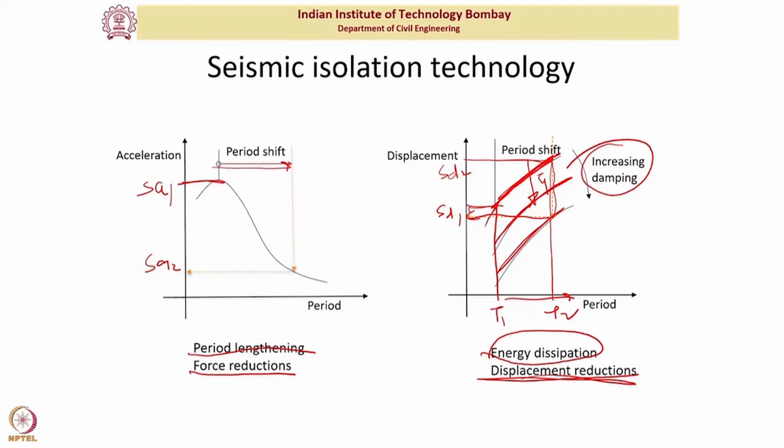So if you increase the mass, it will increase the time period. But consider a typical example. Let us say you have a concrete building, and if you want to design it, can you do much about the mass of the building that you are designing? These structures are more suitable for seismic isolation rather than light structures. So basically, you would not apply seismic isolation to a wood structure.